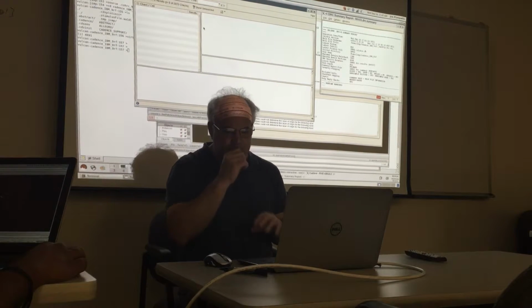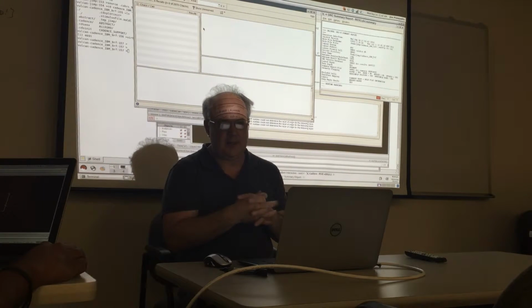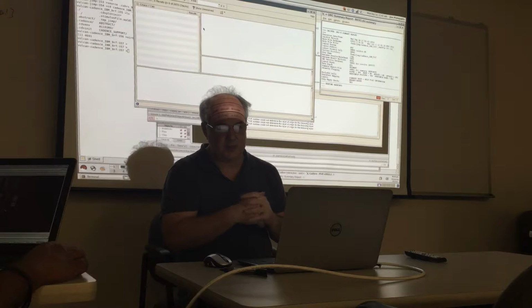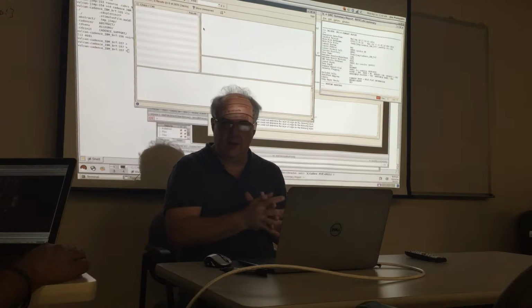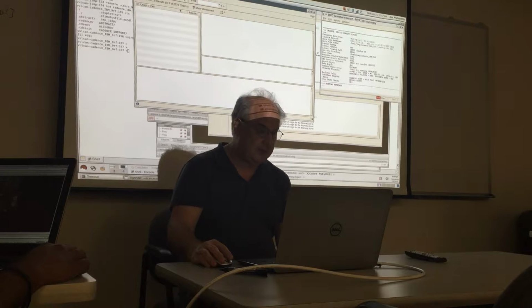DRCs are fairly straightforward to figure out what the problem is. It's usually a spacing or a sizing violation, especially with diffusions. There's lots of rules with diffusions. Then you can go to the layout and you have to fix it, and a half hour later you're ready to do it again. I mean, it depends on how bad the violation is.